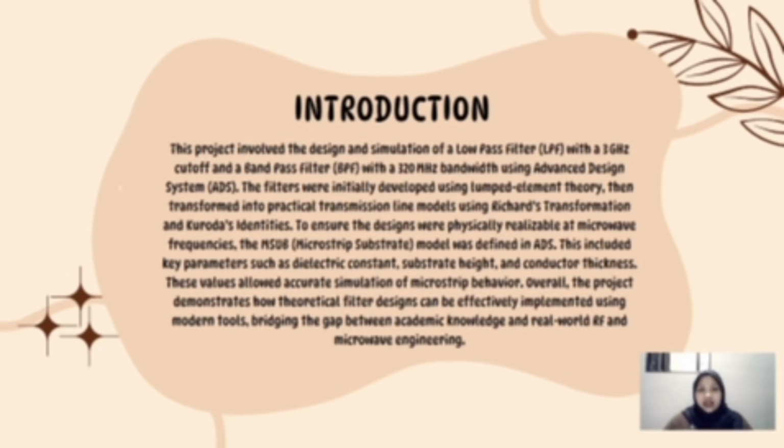Using Advanced Design System (ADS), the filters were initially developed using lumped element theory, then transformed into a practical transmission line model using Richards transformation and Kuroda identity. To ensure the design was physically reasonable at microwave frequency, the MSUB model was defined in ADS. These include key parameters such as dielectric constant, substrate height, and conductor thickness. The values allow accurate simulation of microstrip behavior.